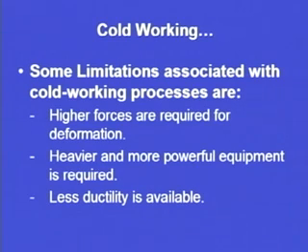cold working operations. Then whenever we are making use of cold working, less ductility is available. So, ductility or the deformation property is less. So, in order to increase the ductility, what we can do is slightly raise the temperature in order to improve the ductility of the metal. So, cold working has a number of advantages over hot working, but there are certain limitation areas which have been addressed in this slide.